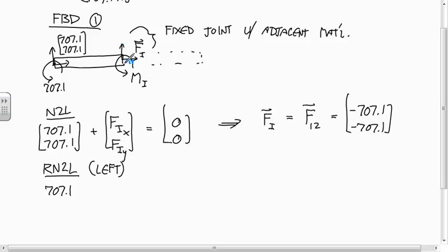And this force Fi, what moments does that produce about the left end? Yeah, only the Y component produces a moment. And I'll just write it first as, if Fiy was positive, it would produce a counterclockwise rotation, right? So that's a positive moment because it's counterclockwise. And so that means that we have the moment arm of 0.5 times Fiy, and then plus Mi is equal to 0.